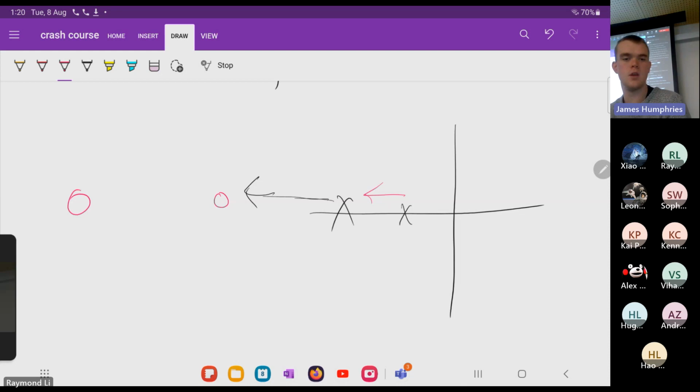All right. So according to the root locus, the closed loop poles will eventually end up at the location of the system zeros. Therefore, adding a zero on the left half plane helps bring the closed loop poles further to the left half plane if the gain is increased, which is stabilizing. It is recommended that the zero is added to the left side of the first real open loop poles, or in the worst case scenario beneath the real part of the closed loop poles. Ah, yes, that's where it comes from.